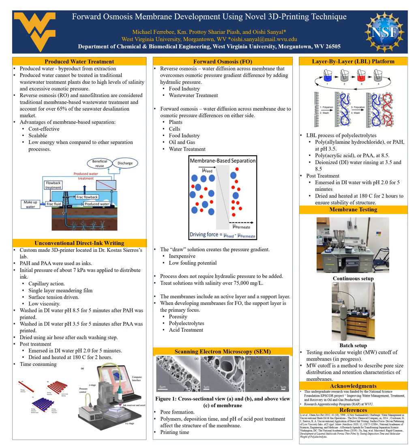Currently, our projects focus on forward osmosis membrane development for unconventional applications, in this case, produced water treatment. Produced water is wastewater that is left over from oil and gas extraction. This type of water tends to have salinity levels over 75,000 milligrams per liter. This creates an excessive osmotic pressure. Reverse osmosis membranes and nanofiltration are unable to treat the water due to excessive pressure.